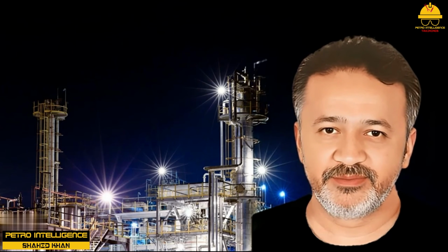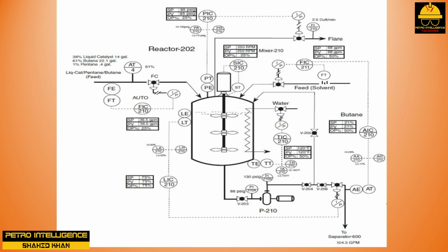Reactor systems. A common type of reactor is the mixing or stirred reactor. The basic components of this device will include a mixer or agitator mounted on a tank. The reactor shell is designed to be heated or cooled and to withstand operational pressures, temperatures, and flow rates. The design may include tubing coils wrapped around the vessel, internal or external heat transfer plates, and jacketed vessels. Hot oil, steam, or cooling water may be the heating or cooling medium.